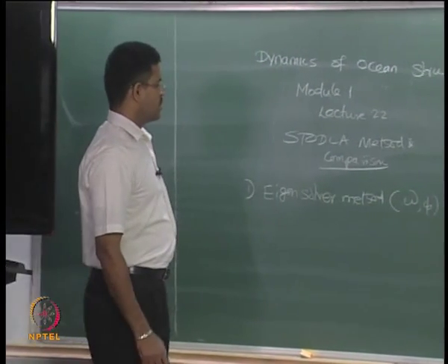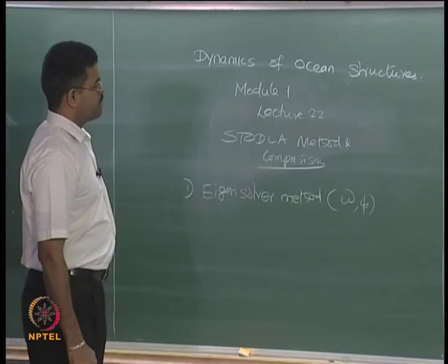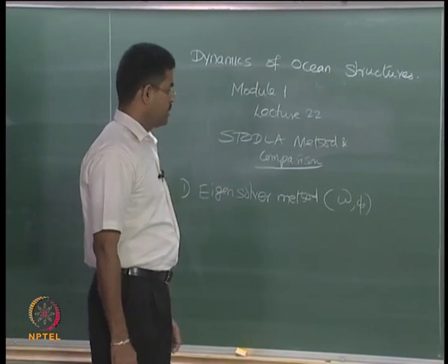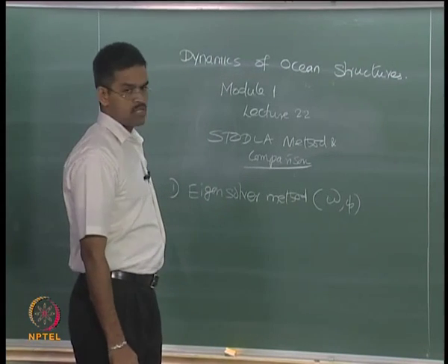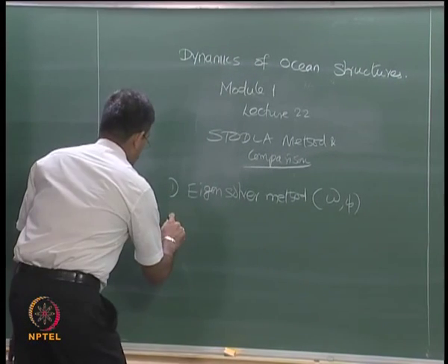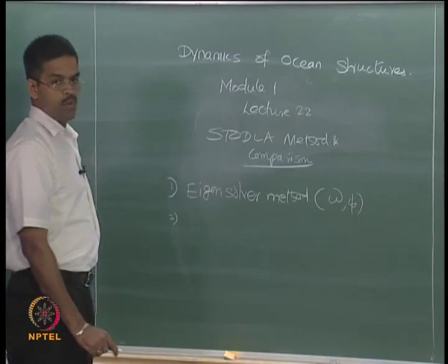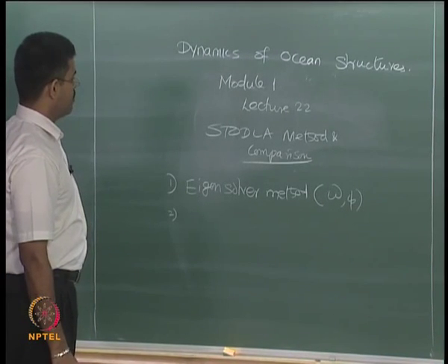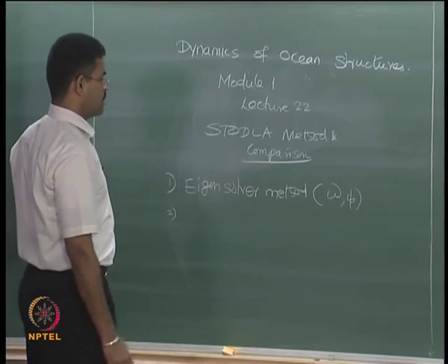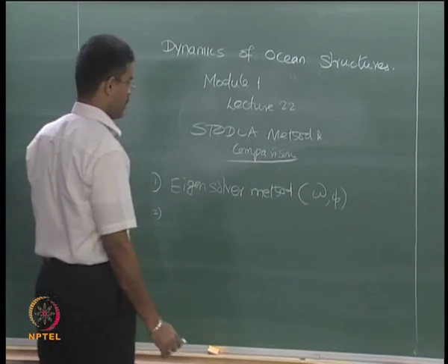We already understood that for larger size of matrices of mass and stiffness, this method will be slightly cumbersome and computationally expensive. So, we look forward for some of the approximate methods or numerical methods which can give me the omega and mode shapes of multi-degree freedom system.